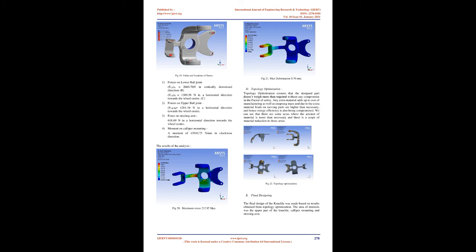Wheel and ground were assumed to be a point contact pair with the patch area 0. Two frictional forces are acting on the wheel in the described boundary conditions. One is the cornering frictional force and the other is the trailing frictional force, hence there are two moments caused by each force, with the cornering frictional force and caster trail causing a clockwise moment and the trailing frictional force and scrub radius causing an anti-clockwise moment.